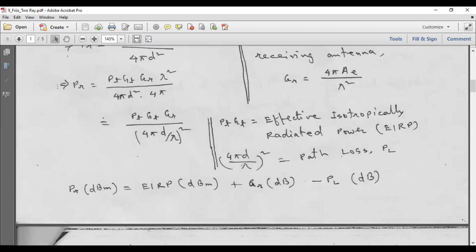Okay, in dB. But just to show that it has used the reference milliwatt, you write it down as dBm. Got it? Yes. On the other side, again you have 10 base log. For the whole thing, you divide by 1 milliwatt. Just try to understand that you are dividing by 1 milliwatt only once, on both sides. Here also you have 1 milliwatt reference to represent this whole power.